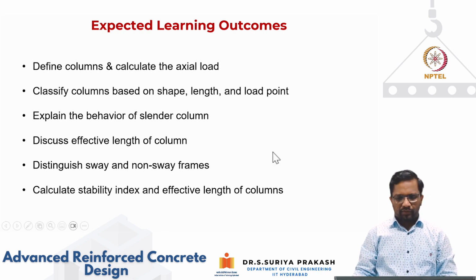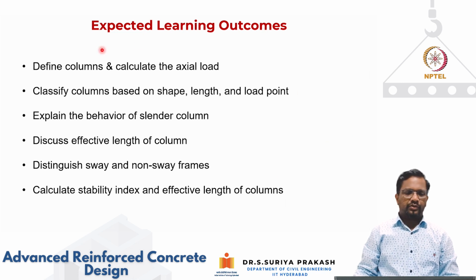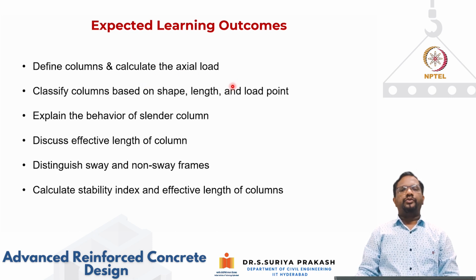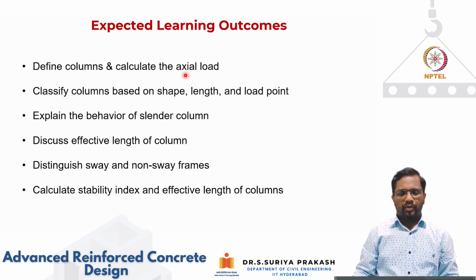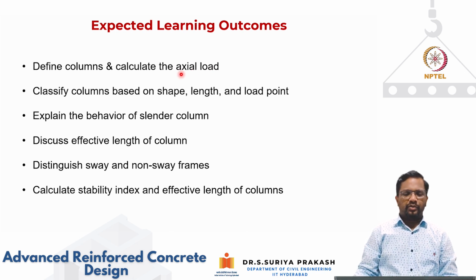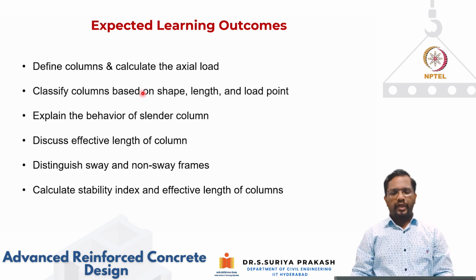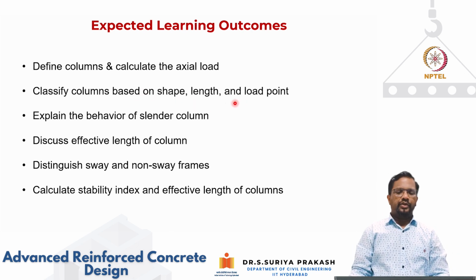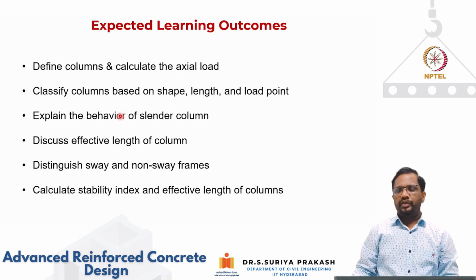After going through this part of the video, the student should be able to define what is a column and should be able to also approximately, let's say for a residential building, calculate the axial compression load that comes onto the columns, then how the columns are classified based on the shape, length, and the loading applications.